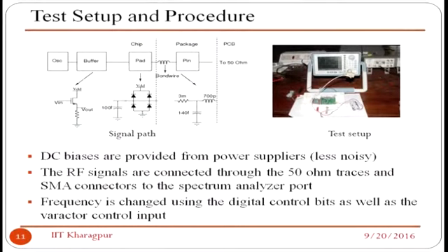Before that, one of the most important parts is that you should have a proper pad design, meaning your pad and pins should be modeled accurately. What does it mean? What information should you have when you talk about the pad and pin parasitics? That should be available from your vendor. Look at here, this is the oscillator, right? And for the oscillator, you need a buffer. This is an important step.